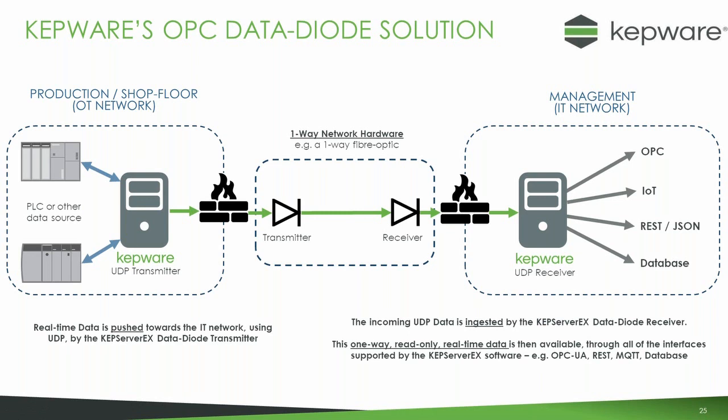For all they know, it's coming from a PLC sitting straight behind that copy of KEPSERVER. So this application is a very innovative way of creating data in a one-directional path. It's also not expensive, because data diode applications have commercially been tens of thousands of pounds, very expensive applications to put together. You can effectively do this one for about £4,000 or £5,000, and it's a very powerful solution you'd end up with at the end.